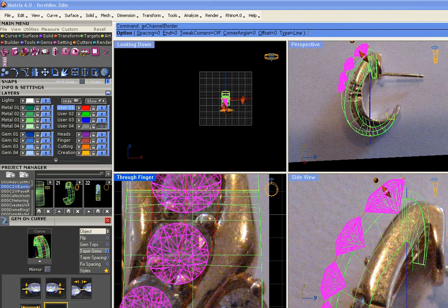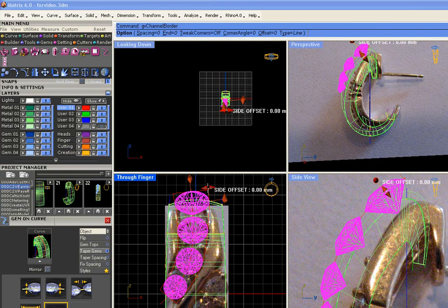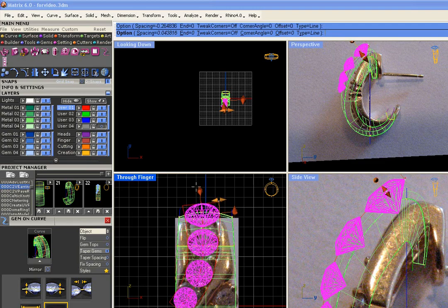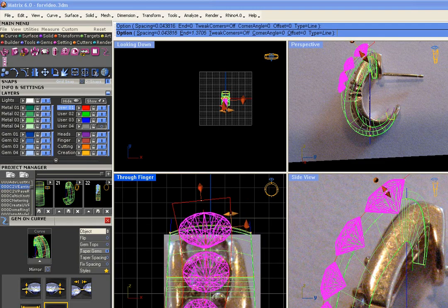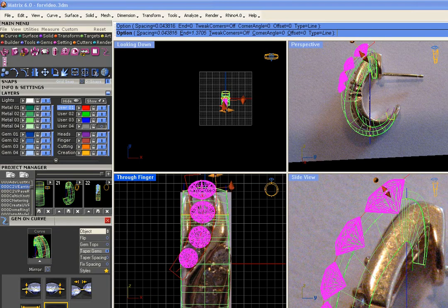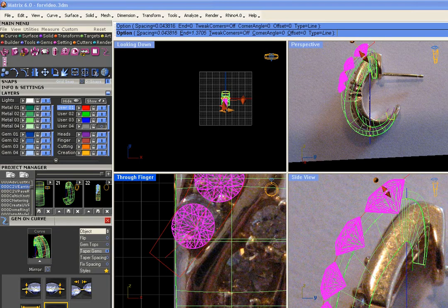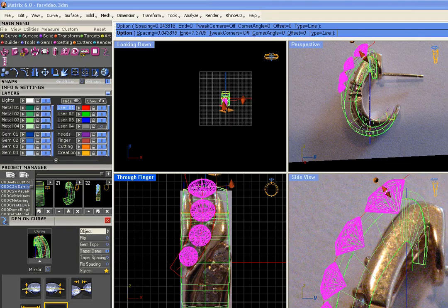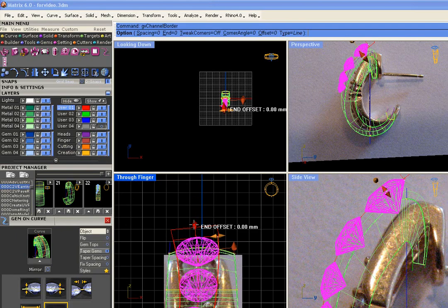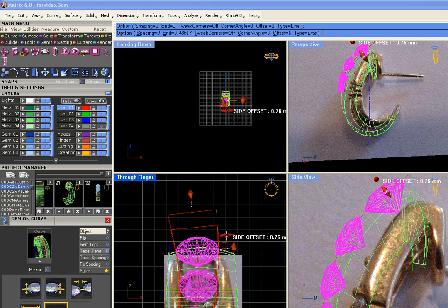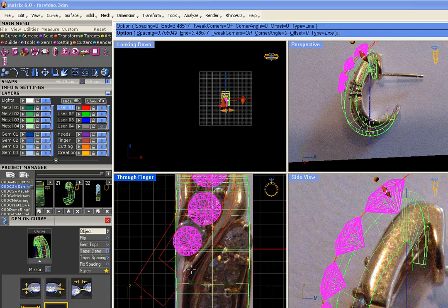Okay, and then figure out how close or far away from the gems you want this curve. We're going to place a profile on it. We're also going to give it a little bit of distance at the end so that we can place this profile sort of off down here. It's going to be this piece right here, this little guy. Okay. Press enter to place it. Now put these back in the tool, run the tool one more time, and you get another instance of this. So go ahead and place these past that to set up for a 2-rail sweep. Okay.